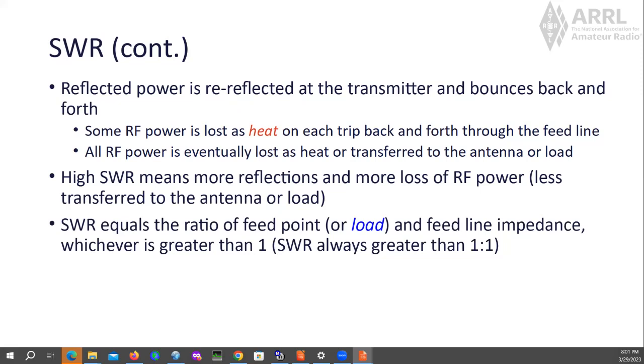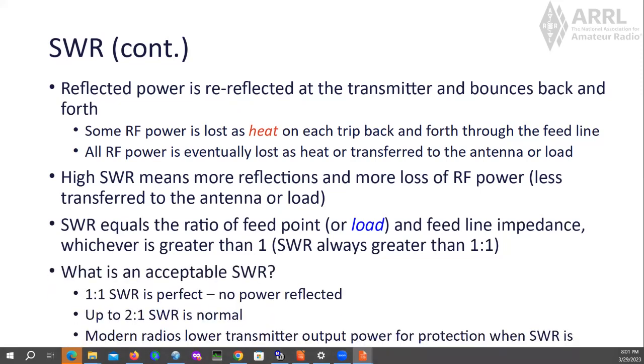What is an acceptable SWR? 1-to-1 SWR is perfect, no power reflected. Up to 2-to-1 SWR is normal. Modern radios lower transmitter output power for protection when SWR is above 2-to-1.